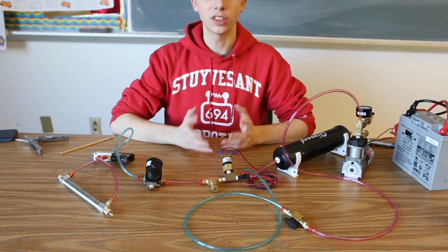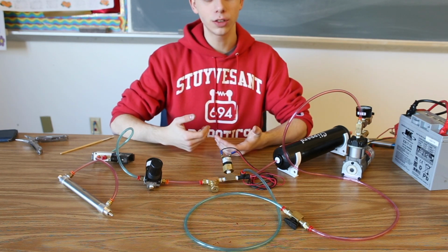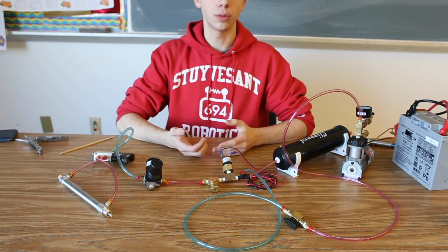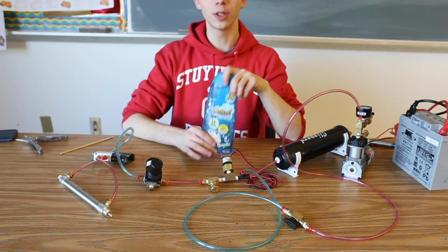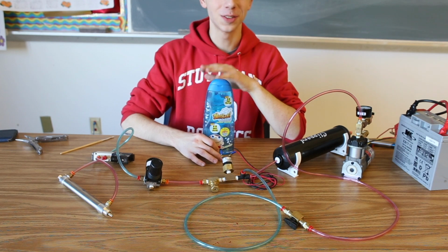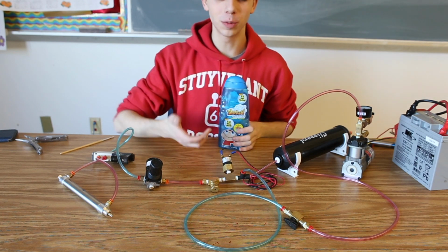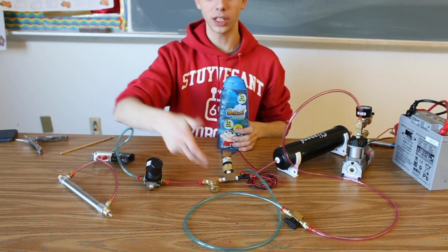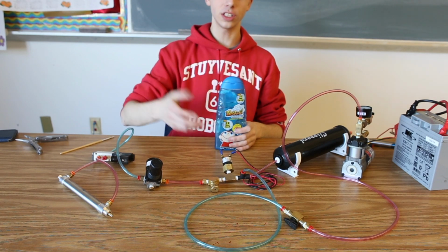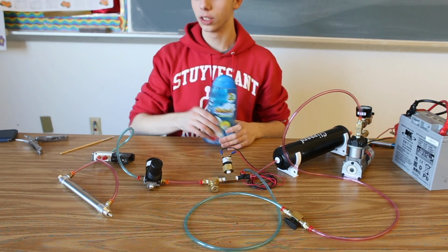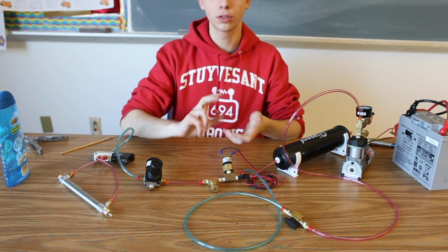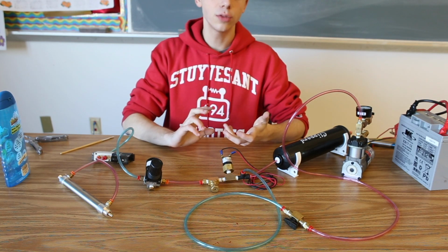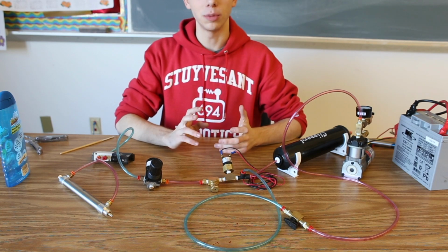Now, when you are assembling your pneumatic system, you may encounter leaks, which is a huge detriment to your system. When you're building your pneumatic system, you may want to use bubbles to find these leaks. Just smear some bubbles on each brass component, each plastic component, and you'll start seeing bubbles form if there's a leak. If there's a leak, you may want to re-Teflon your parts or just screw in a bit more. If that doesn't fix it, I suggest throwing out the part because it may be faulty.